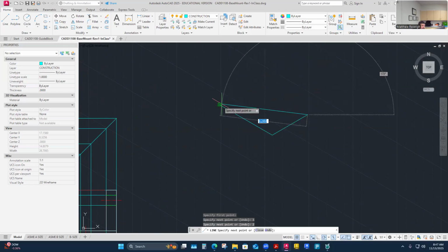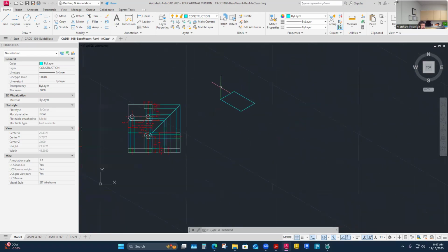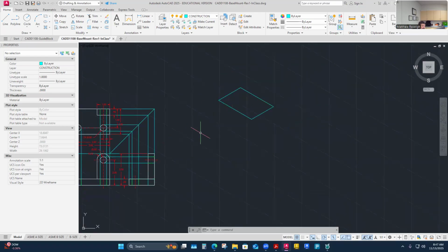And then here you can also use your object line tracking. Similar to how I would draw on the other regular planes, I can highlight and target points like this and snap them together. So that's the base footprint of that object, 3 by 2. Then it goes up whatever the height is. I'll just build the whole glass box actually.